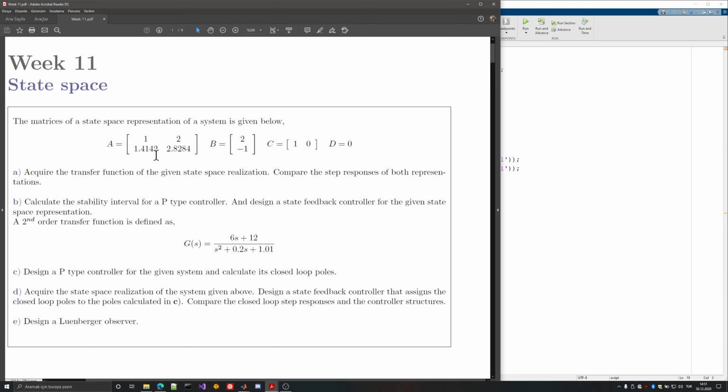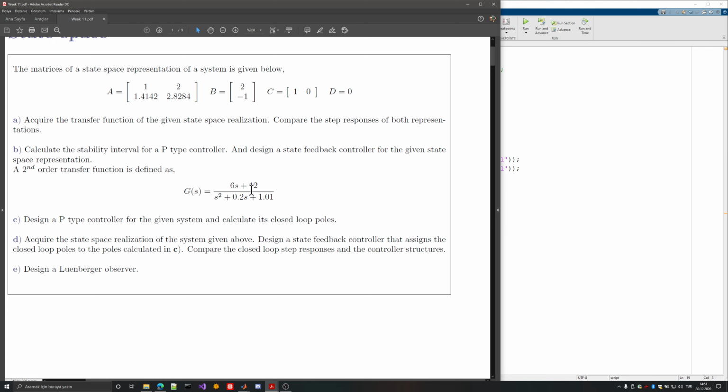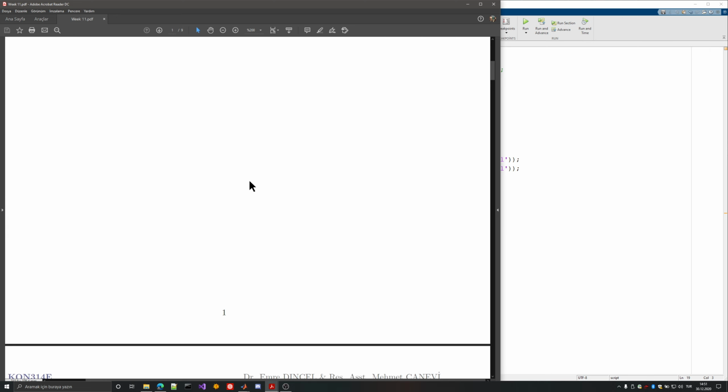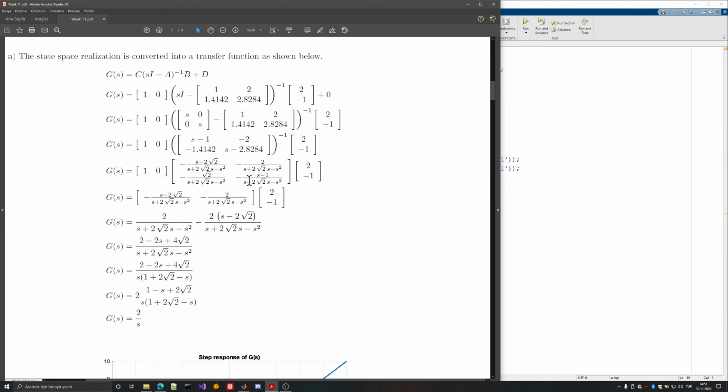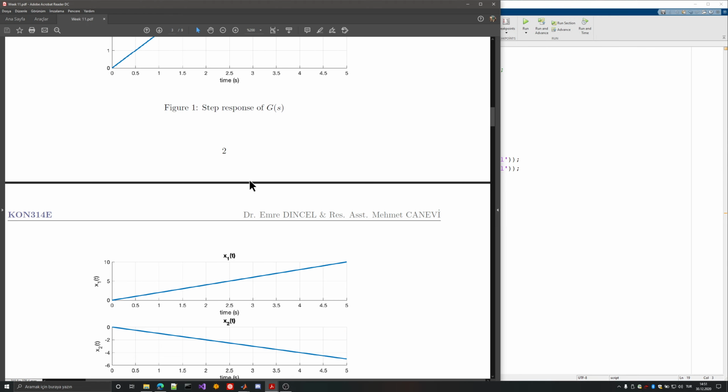They are the same. The eigenvalues of A are the poles of this transfer function. So by the way, you cannot see the zeros directly from here, but the responsible one for the zeros is the C matrix. And you should check out these notes here maybe, and your own notes.